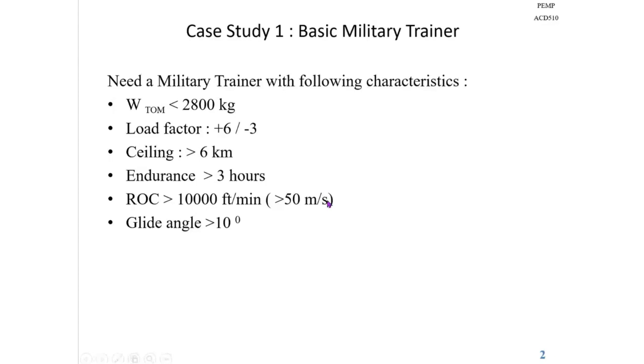Endurance 3 hours will tell you how much fuel you're going to carry. Ceiling 6 kilometers will tell you something. Load factor plus 6 will tell you something. And rate of climb 50 meters per second will tell you something. So from these requirements, you should start deriving different components of the design. Okay, so that was the first one.